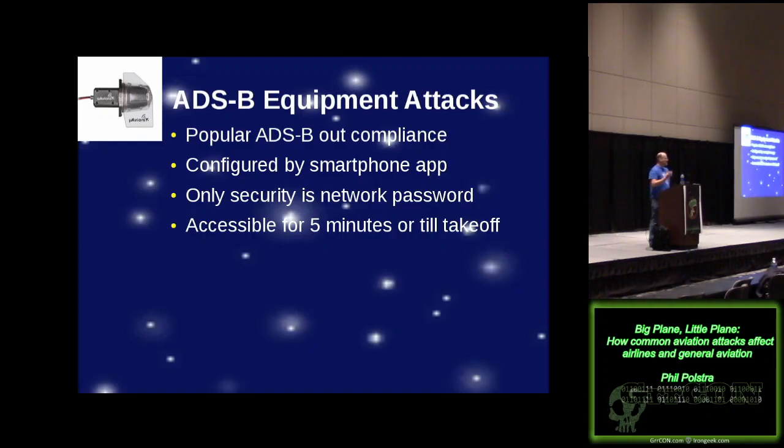It actually uses the power wires that go into this unit as an antenna to receive the transponder transmissions to go, oh, your transponder just fired, and here's the code that it just sent, so let me take that information and put it together, and I'm going to transmit the appropriate ADS-B signal that goes with that transponder reply, right? Which is kind of cool, right?